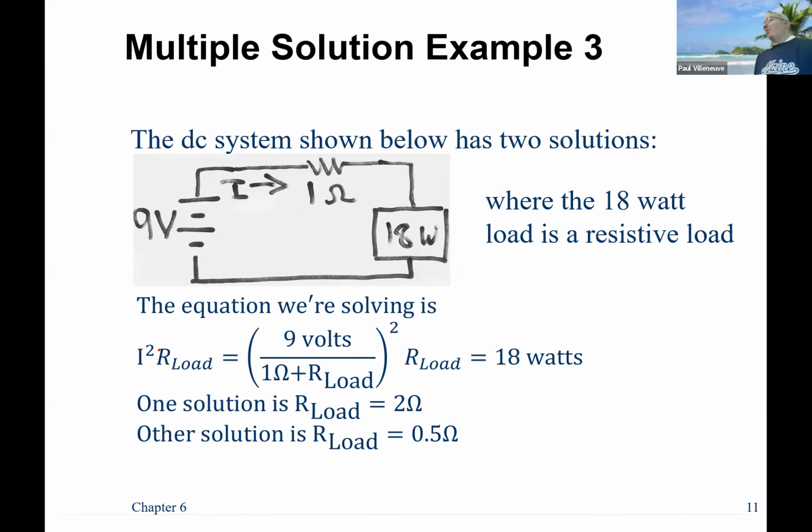So now we're ready to apply the Newton-Raphson load flow algorithm, and it's the concept of sequential linearization. So you're going to linearize about a point. You're going to do some work and see if you're close to the final answer. If you're not close, you're going to linearize about a new point, do some work, and see if you're close to the final answer. If you're not, rinse and repeat. So it is essentially an iterative process.